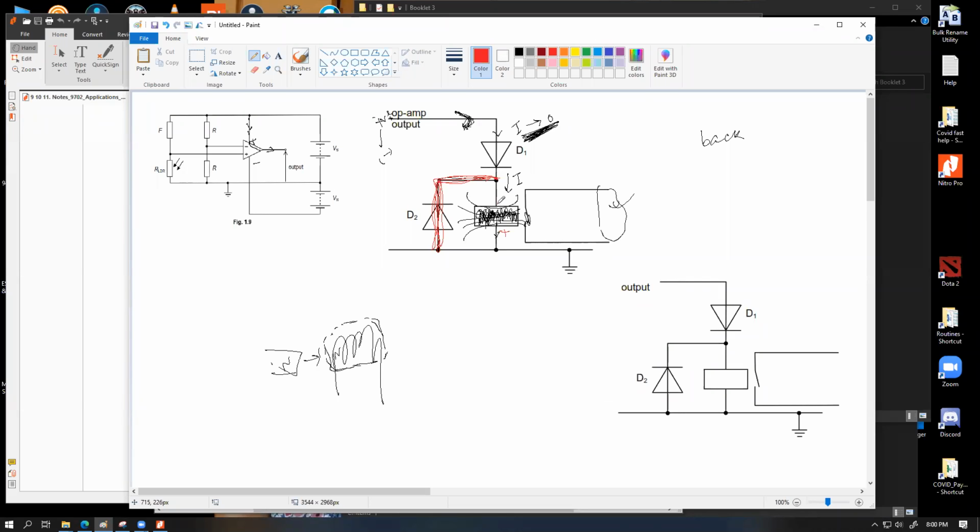So this is the low voltage connection. This coil is trying to produce a very large back EMF, so it is trying to pull a very large current through here. We are providing this connection path so that this solenoid, as it is losing its current, as the current is slowly becoming zero, can pull its necessary current from the ground connection, and we can have this high current flow through this pathway, and it can essentially die within this loop of the circuit. So this is the reason why we need this secondary pathway.